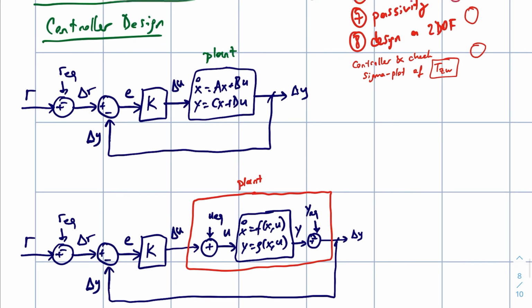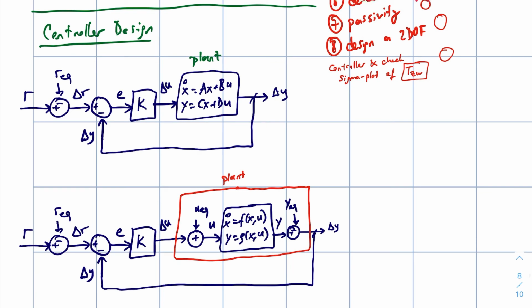Here it would be a better idea to compare them. This is your linearized plant, and this is your true plant, the nonlinear dynamical system. You just design your K, and then test your K on the real nonlinear dynamical system. Of course, you will like to have some H infinity, or mix sensitivity, mu sensitivity type of control algorithm to design a controller.